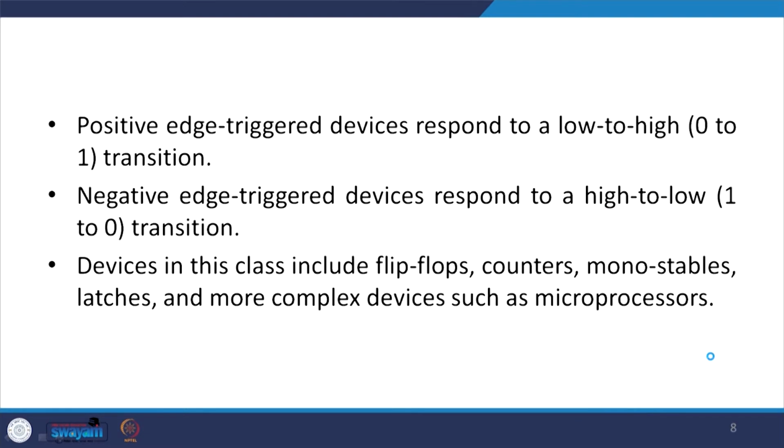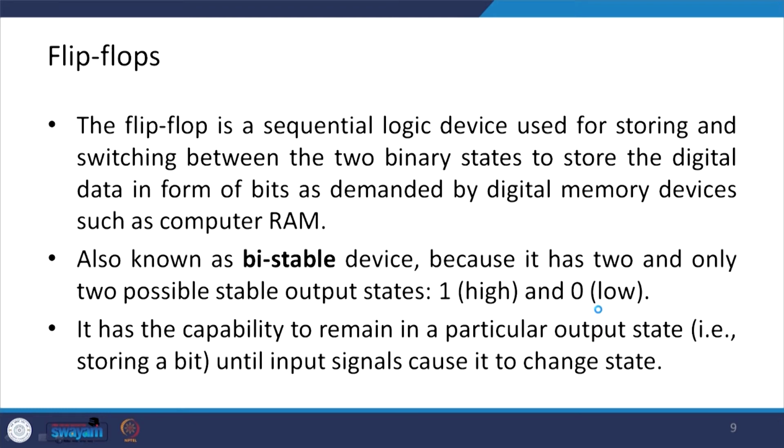So, positive edge triggered devices respond to low to high, that is 0 to 1 transition, whereas negative edge triggered devices respond to high to low, that is 1 to 0 transition. Devices in this class include flip flops, counters, monostables, latches and more complex devices such as microprocessors.